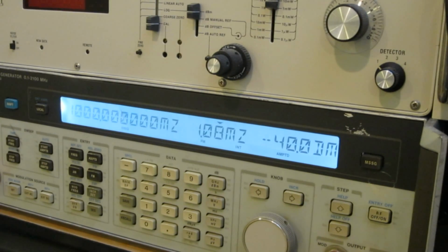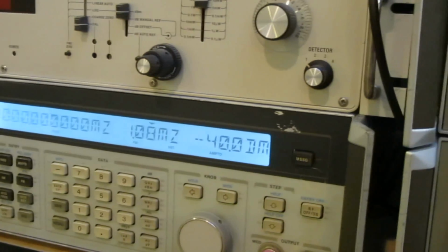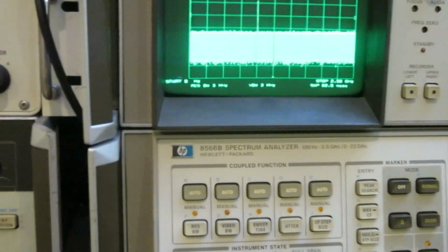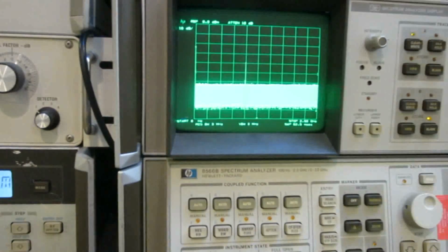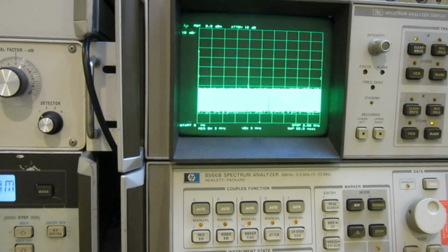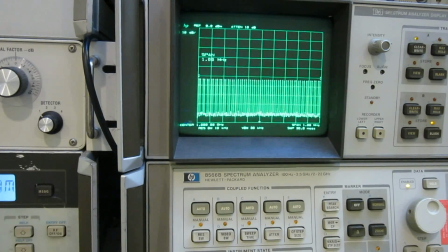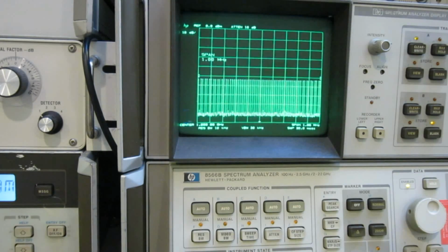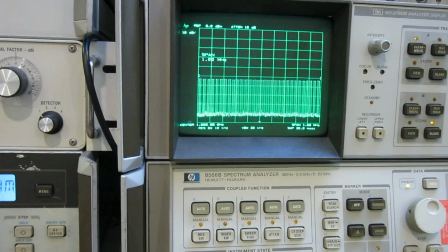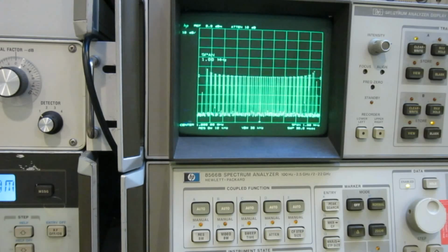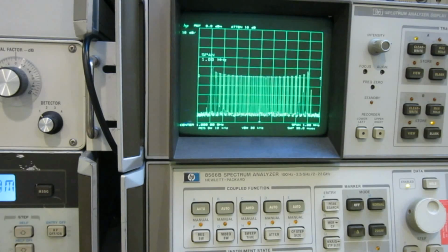So now let's come back to the frequency spectrum analyzer. Again, right now it's at default. So this is a 0 to 2.5 gigahertz. And again, I'm going to put my center frequency to 1 gigahertz and put a frequency span to 1 megahertz. Actually, right now, let me lower the frequency band a little bit, because remember we set it to 1 megahertz, which is pretty big.